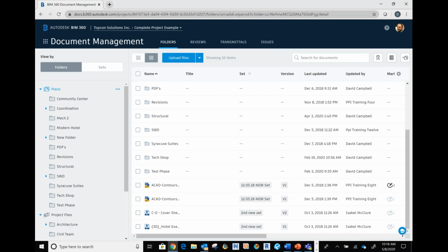Initially, when you first open or load the model to BIM 360, it is going to take some time. But utilizing that desktop connector, which Shelly touched on a bit, it does actually cache those documents, any of those drawings, the DWGs, the RVTs, whatever type of model you're working with. Once it caches that model locally, it's going to open up a lot quicker in the future. It's really just that first opening that takes some time.